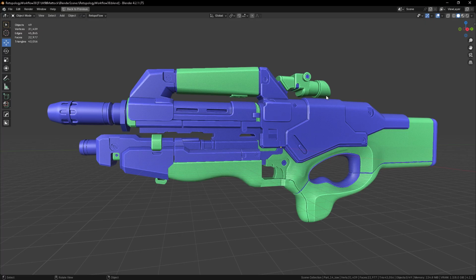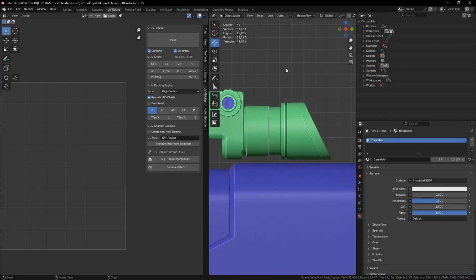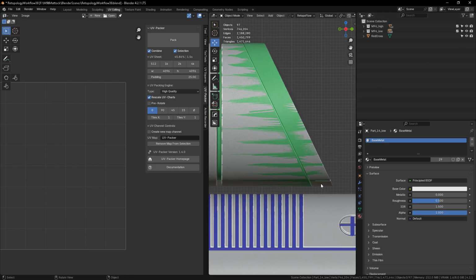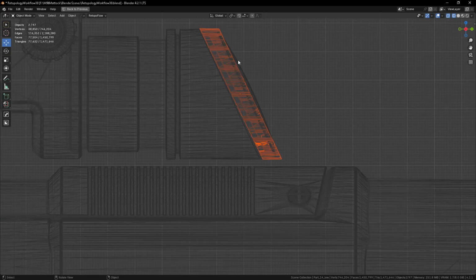So before going ahead, I'd like to do a little tweak to my scoop here. Press Control Spacebar, and let me turn on my high resolution mesh. So I want to select these meshes, both high and low resolution mesh. Okay, and then switch to wireframe view.